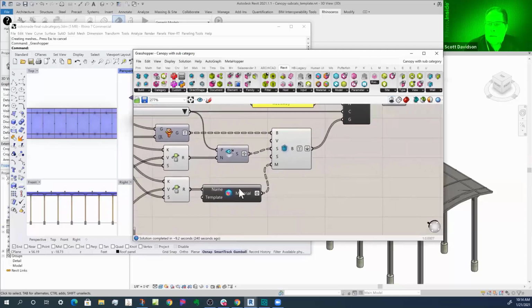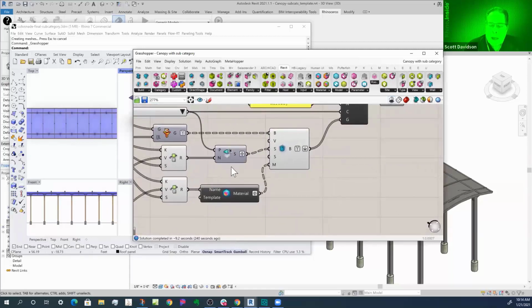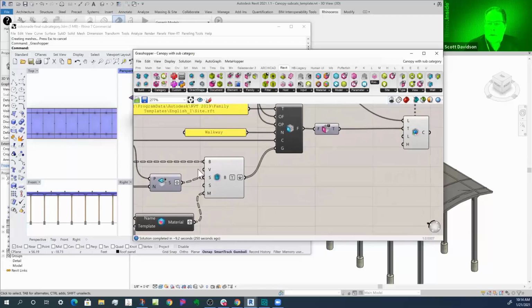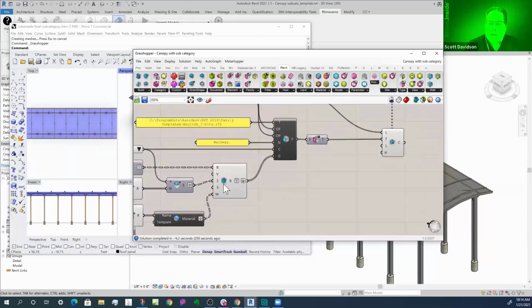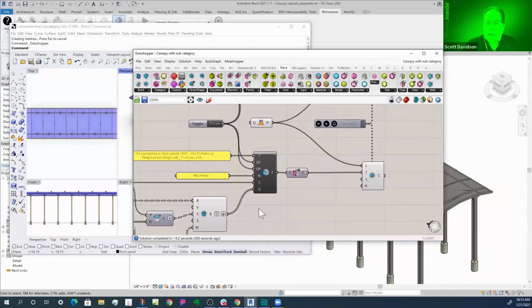And then I can create the subcategories if I need them. I can also create the material names if I need them. If they don't exist, they'll get created. Then I push those all into essentially a form mixer, which mixes all the subcategories with the forms and all those pieces. Then we get to the family again, a new family. This is an on-site family because I'm going to use subcategories. So I have to find a category, or a family, I can use subcategories on.